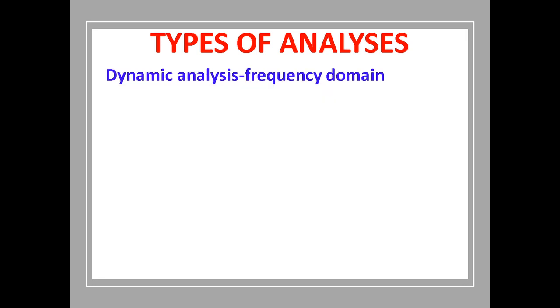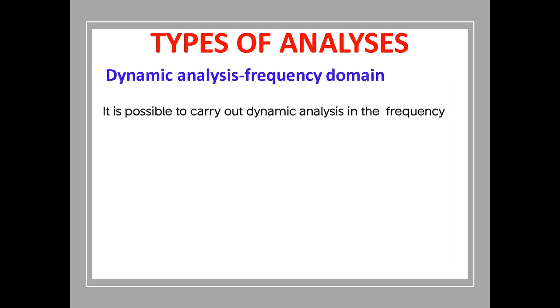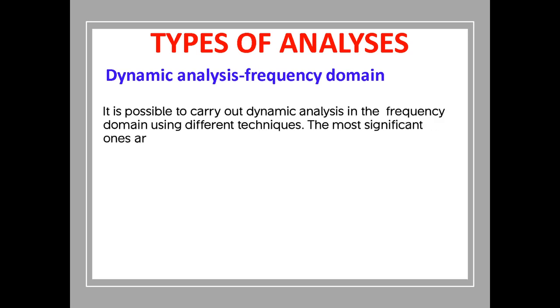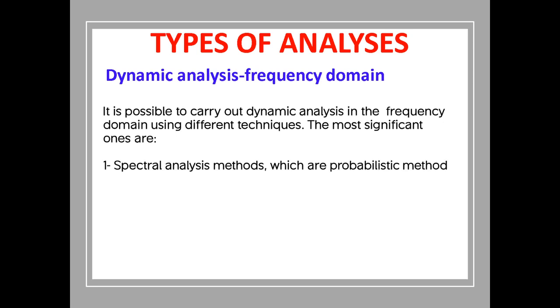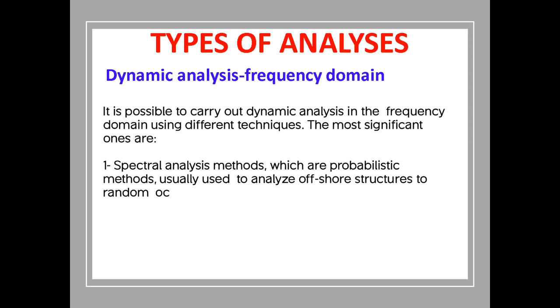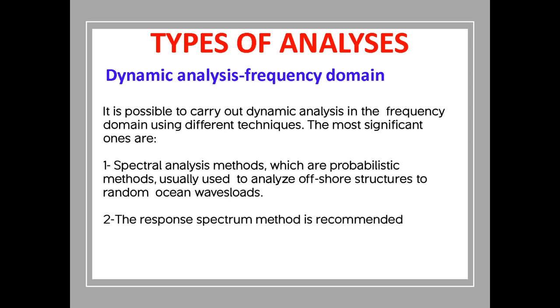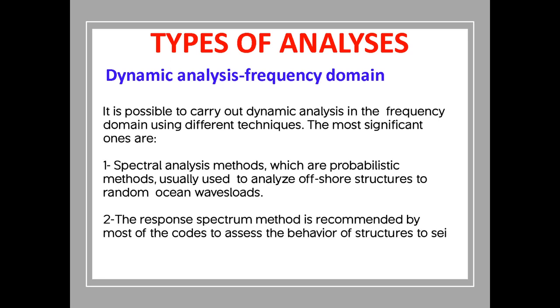It is possible to carry out dynamic analysis in the frequency domain using several techniques. The most significant ones are spectral analysis methods, which are probabilistic methods, usually used to analyze offshore structures subjected to random ocean wave loads. The response spectrum method is recommended by most of the codes to assess the behavior of structures to seismic loads in the linear phase of vibration.